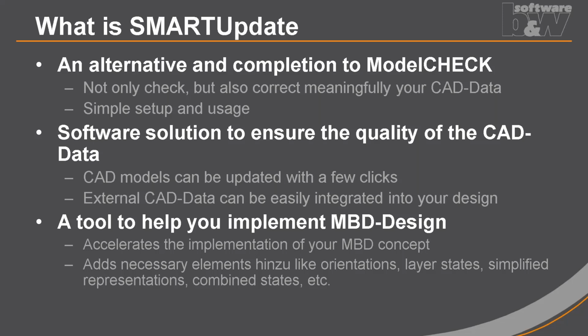And maybe the most important, it's a very helpful tool to help you implement the embedded design concept. You can set up all the necessary elements like orientations, layer states, combine states, and so on, everything that belongs to the embedded design, and add them all at once to all your models.